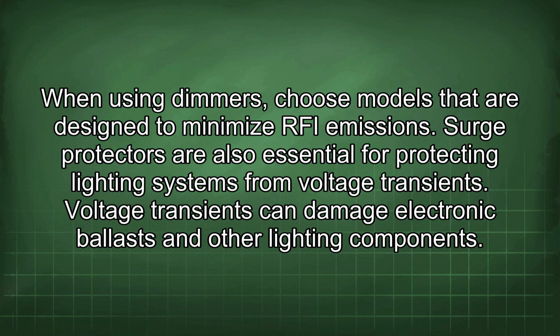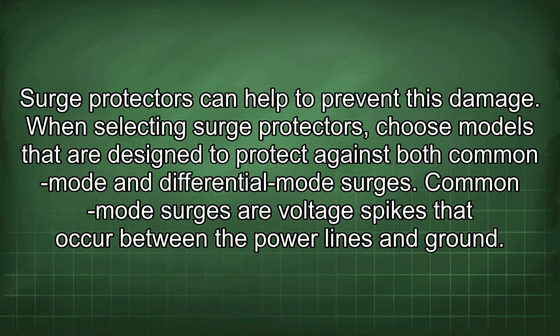Surge protectors are also essential for protecting lighting systems from voltage transients. Voltage transients can damage electronic ballasts and other lighting components. Surge protectors can help to prevent this damage. When selecting surge protectors, choose models that are designed to protect against both common mode and differential mode surges.